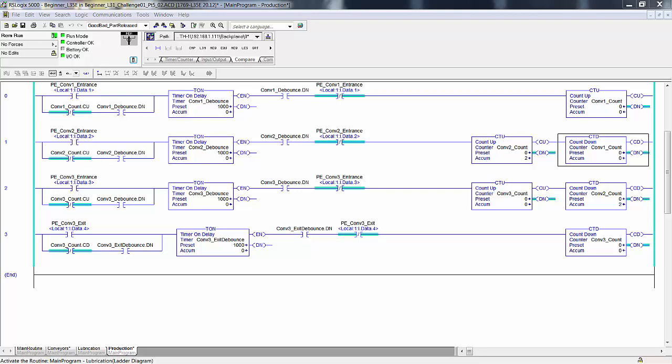The singulation would have to be adjusted for each carton length to coordinate the available length of the conveyor to the carton lengths. In other words, you would have to increase or reduce the space between each carton. So there's no way you could have a carton partway on the next conveyor and have one partway on at the same time. In other words, on conveyor 1, you have one half on conveyor 1, and then at the other end of conveyor 1, you have it one half off and half on the next conveyor. You could adjust the singulation space to avoid that, which means you might have to really increase the space.